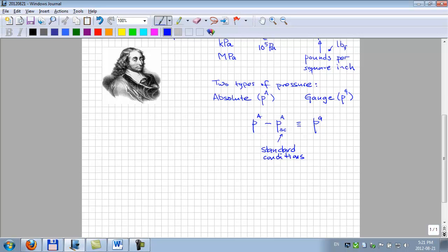Because in water, you generally gain 1 bar for every 10 meters you go down. Okay? So if you go 100 meters down into the water, then it's 1 bar here plus 10, right? For every 10 meters of water, you approximately add 1 bar. That's a static column of water. We'll learn about that later.